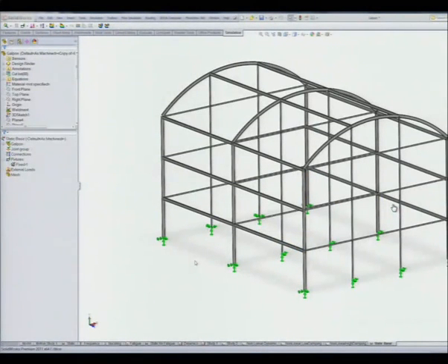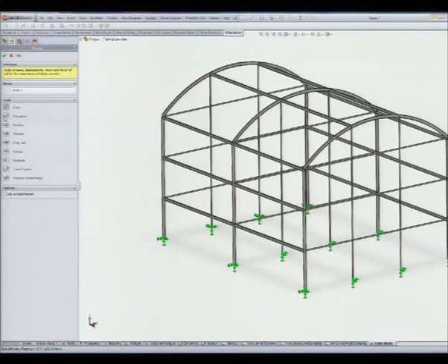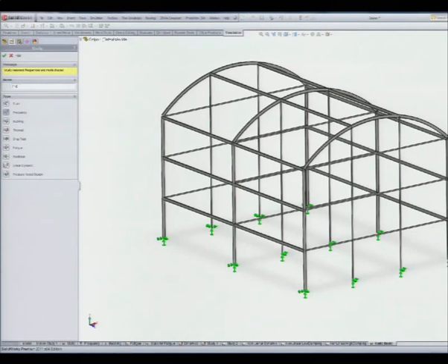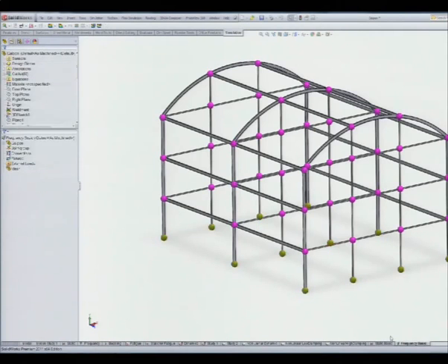Okay, we already set and analyzed static analysis. For this kind of structure, what other analysis will you run? Buckling, frequencies. Yes? I will show you only frequency, how to set the frequency analysis, because it's easier than the static analysis. I'm interested only in natural frequencies. So, what I need is, the model is there. I select frequency analysis. And what I need is material and boundary condition. That's it.